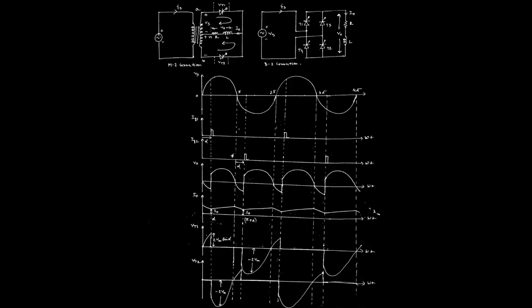If one switch starts conducting, then the other switch is reverse biased and in the off state. It is evident that the conducting switch works as a short circuit, so no voltage will appear across it. But then, how much voltage will appear across the second switch?